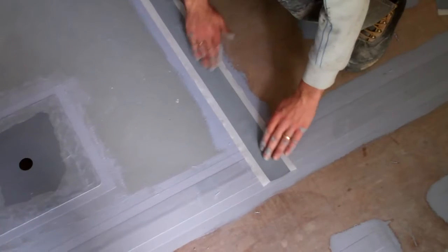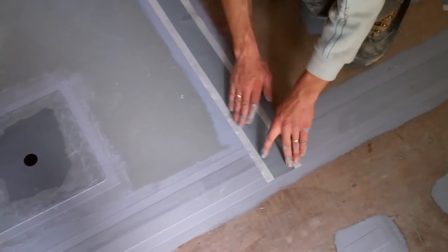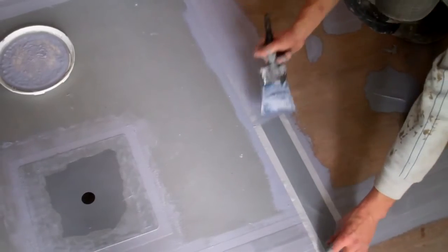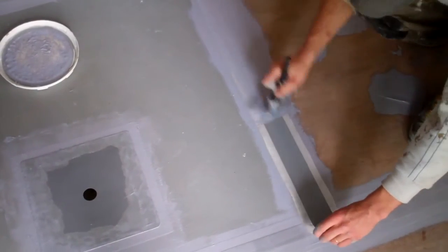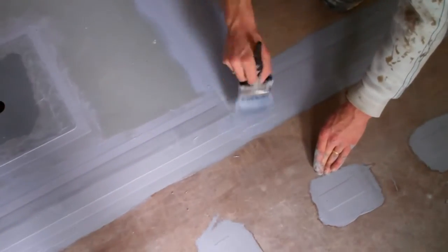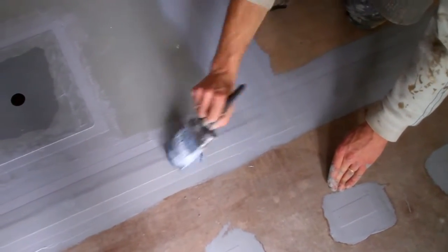Aquaproof tape must also be applied over all screw heads. Most of the screw heads will be along the edges of the flooring sheets where they will be covered with the jointing tape anyway, but individual screws that are in the middle of the sheet can be covered with a small patch of aquaproof tape.